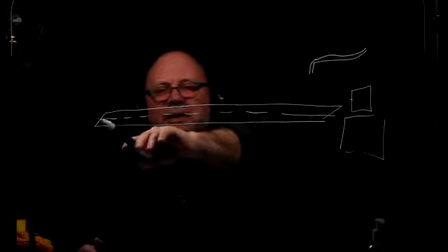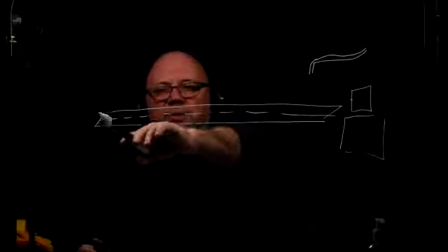So once we pull the wire all the way to the back, we're not going to cut the wire yet. Right? We're going to mount it somewhere, physically preventing it from being pulled back. And we're going to strip the wires and bind them with wire nuts, so the two ends don't become shorted by accident.